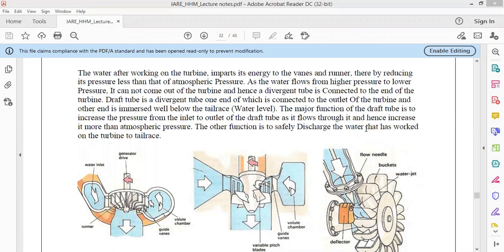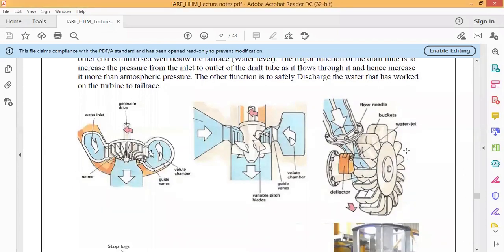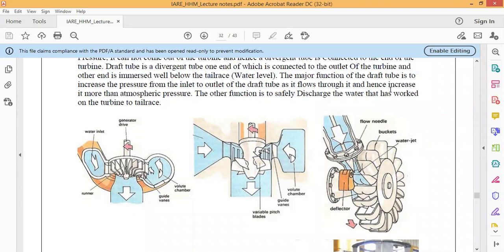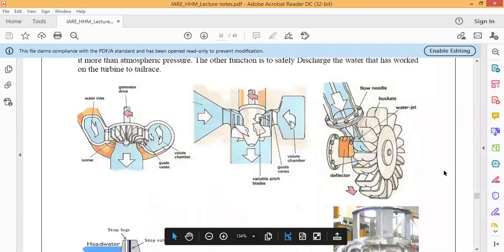So to avoid any such damage to the constructions of turbines, which are actually very costly and use a lot of economic resources for power generation, we use this draft tube for safety, so that it dissipates the energy safely which is coming to run the turbine. It will just guide the system and dissipate the energy of water from higher to lower.